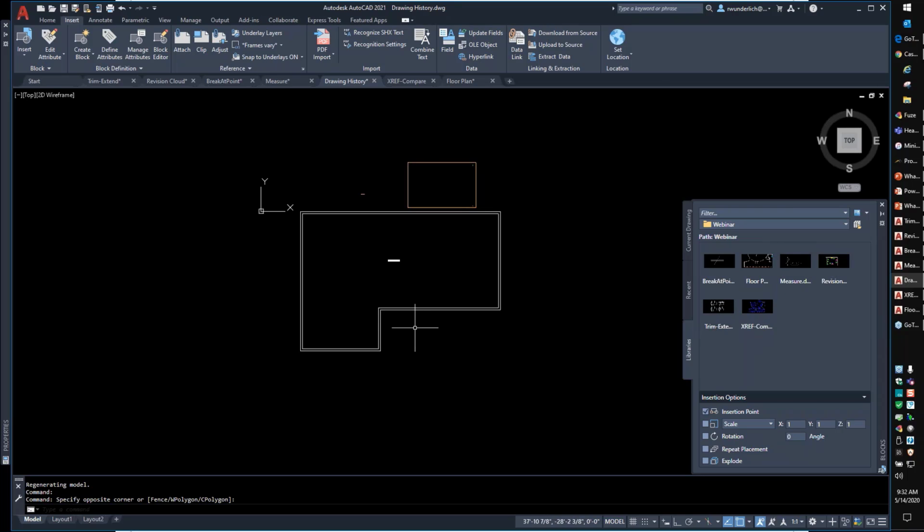Good CAD management said, yeah, in 2020, blocks palette for me is extremely slow to open. Is that me, or is there just a fix for that in 2021? Number one, I would ask if you were fully updated yet on 2020. I know that 2020 does have some updates. There's an AutoCAD 2020.1.2 for sure that you do need that does help with some of the block palette performance. The other things that can cause problems in block palettes is making sure that all of your Windows updates are done. The graphics drivers need to be fully updated as well. And there are some other things we could certainly look at for that.